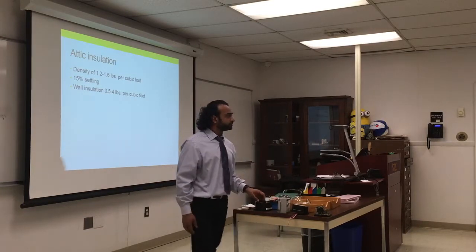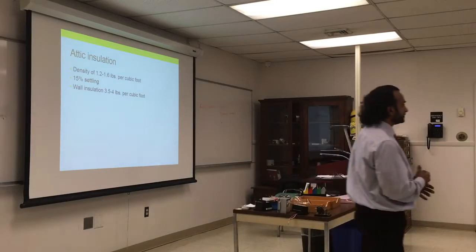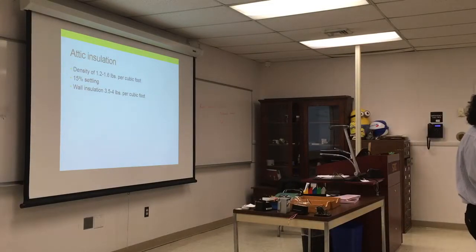The soffit vents are going to keep the attic cold. Air flows through the gable vents and creates pressure from the soffit vents to keep your attic cold. And then humidity can go from the soffit. But for venting, any kind of air from inside the house should not go into the attic cavity. It should be put completely outside.